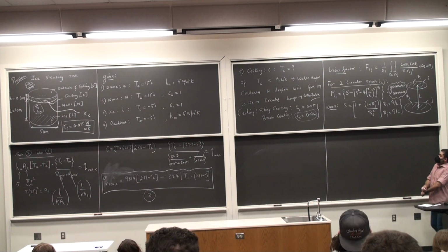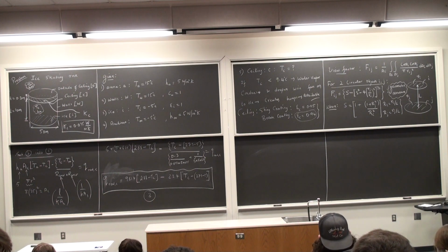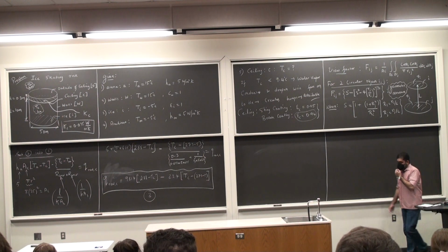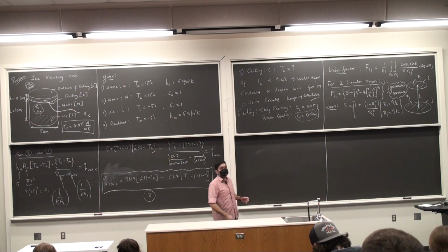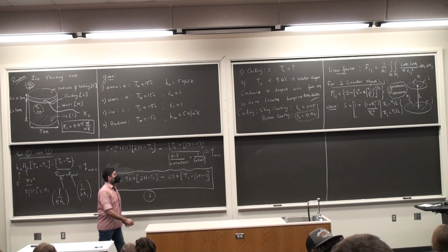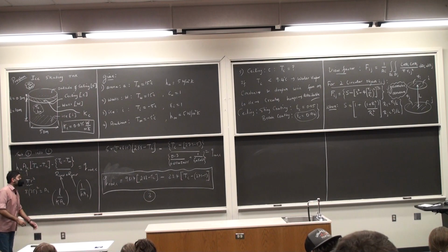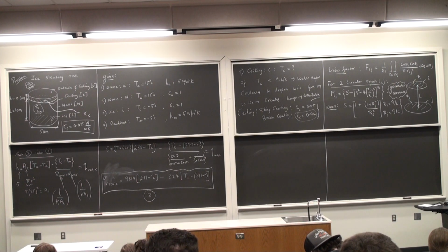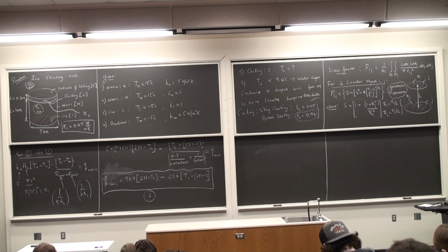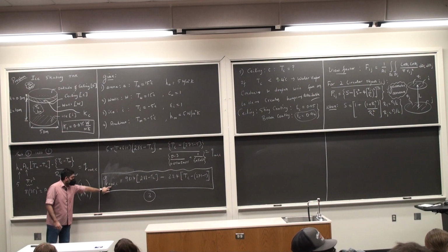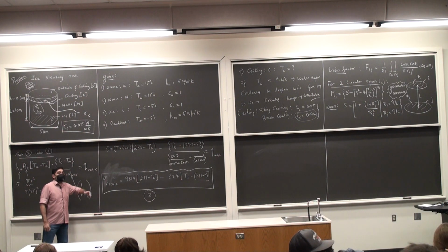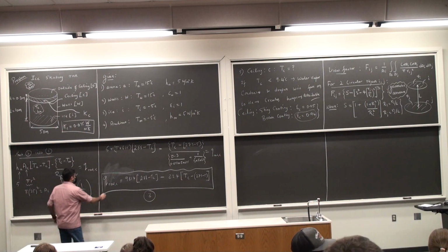So the basic idea is I don't know TC. I need to operate on the idea that I have radiation within an enclosure, so we know how to do this using the resistive networks. But there is conduction and convection as well, so we have to somehow bring those into play. We focus on the ceiling because that's the area of interest for us. And then once we have the network done, this is one equation. Now the whole ball game is to find Q radiation C using the thermal resistance networks. Okay, so to obtain this,